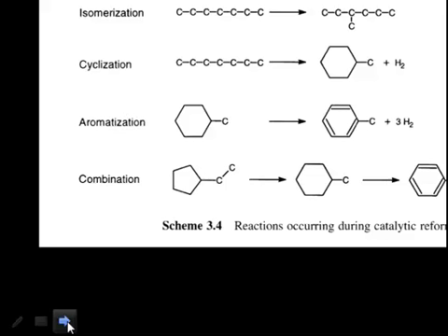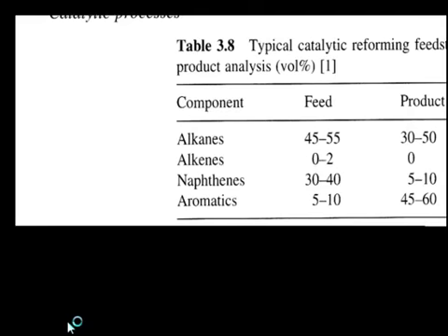In this one, carbon is added from the side chain to have the cyclic ring of 6 carbon content, and then we can have this benzene ring after removal of the hydrogen. So these are the different kinds: isomerization, cyclization, aromatization, and the combination of any 2 or 3 of the processes in order to get the reforming. Reforming makes us get the desired composition in the product.